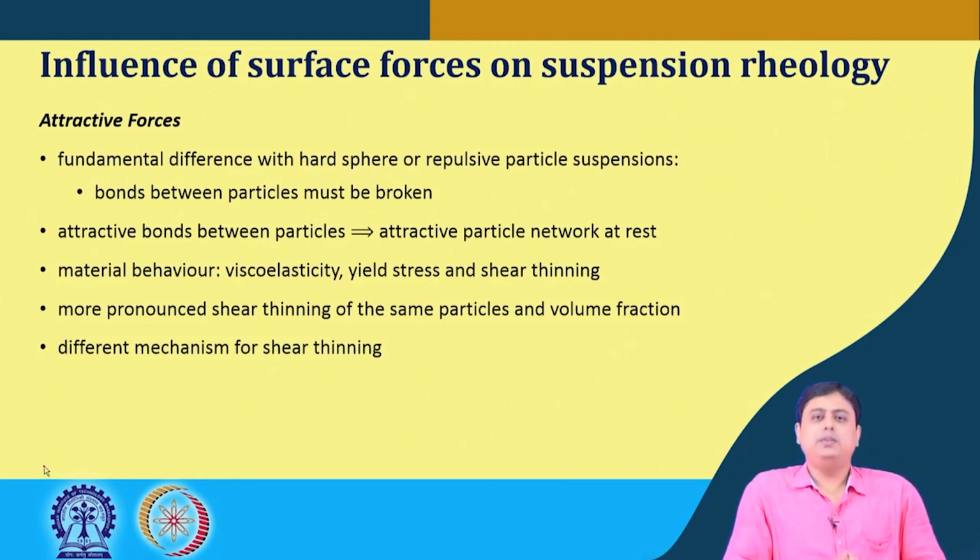Here the suspension behavior is typically viscoelastic, or shows yield stress or shear thickening. The viscoelastic nature is a combination of solid and fluid behavior. When some shear is applied to deform the material, some of the energy is stored and some is dissipated as viscous dissipation, and when the force is withdrawn, it returns to the original state.